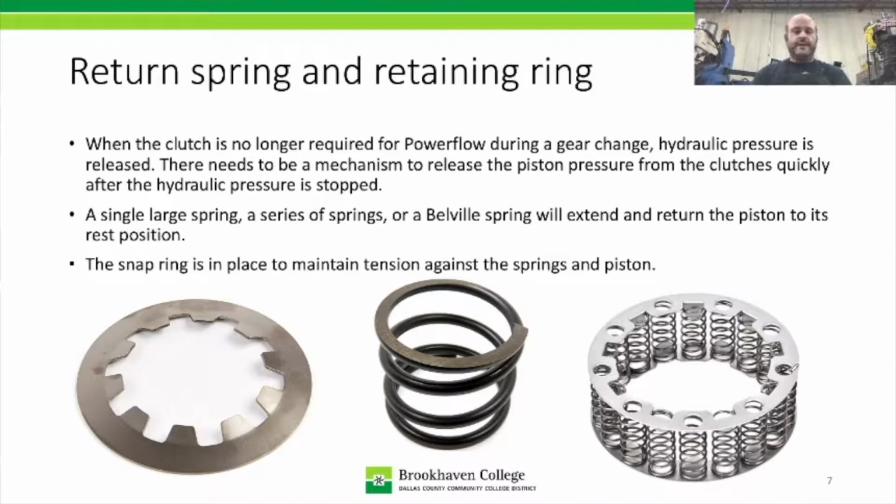Well, same thing here, but even more important is that we don't want to go from one gear to the next to turn off a clutch and have that clutch still be applied, because what will happen is that you'll actually get a drag. If that's a driving clutch, you'll be trying to drag it into one-to-one if another driving clutch is applied. Or if it's a holding clutch, let's say it's supposed to turn off and then the next clutch is going to be a driving clutch that turns on, you'll actually be locking the transmission down because you're trying to drive too many pieces at different speeds, and it'll cause it to bind up.